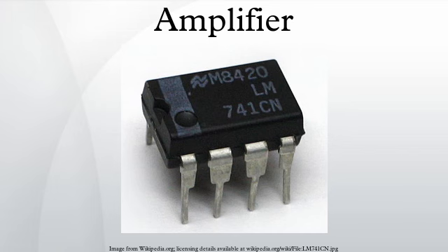Video amplifiers. These deal with video signals and have varying bandwidths depending on whether the video signal is for SDTV, EDTV, HDTV 720p or 1080p, etc. The specification of the bandwidth itself depends on what kind of filter is used, and at which point the bandwidth is measured. Certain requirements for step response and overshoot are necessary for an acceptable TV image.